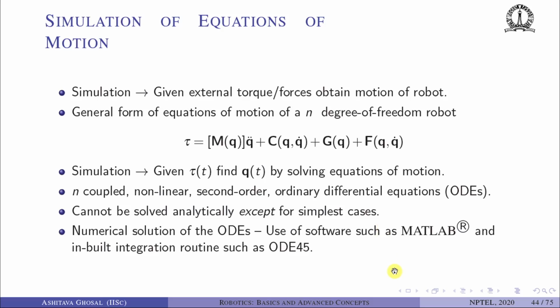We use a software tool such as MATLAB, which has inbuilt integration routines. For example, in MATLAB there is something called ODE45. ODE45 is a predictor corrector method, fourth order predict and fifth order correct, based on Runge-Kutta methods.